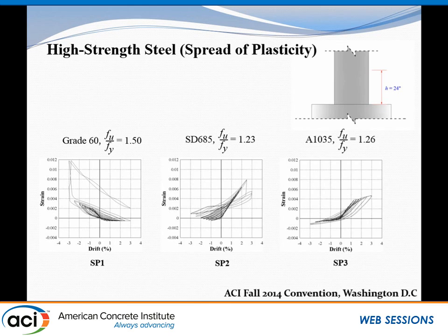Apparently, the longitudinal reinforcement in specimens SP1 and SP2 yields up to 3% drift. And they also indicate one important thing that was found 40 years ago: the existing yield plateau contributed no or negligible deformation. So I just repeat the work of Professor White again.